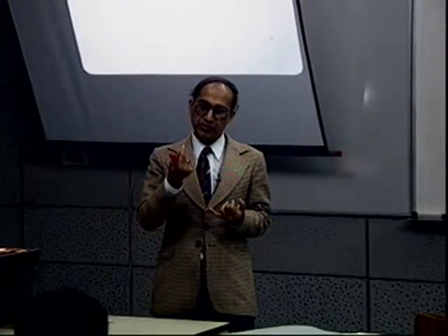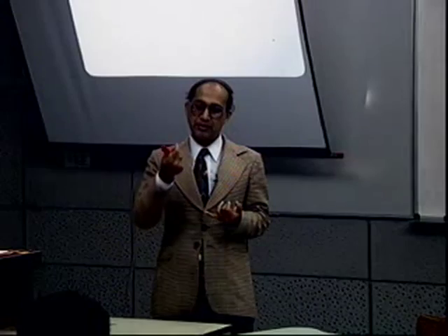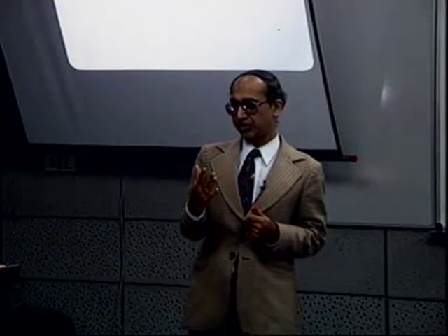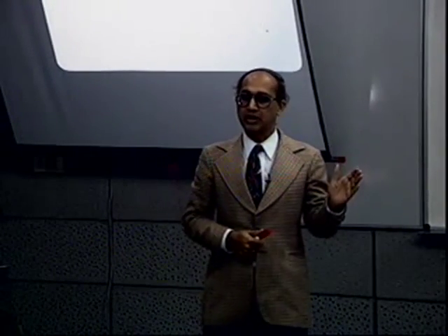Now next we went on to say that there is another phenomenon that takes place whenever the flux is going through a cycle. We observe a phenomenon called magnetic hysteresis. So the core goes through a hysteresis loop, where energy is taken at each cycle from the source, but that much energy is not totally returned to the source.